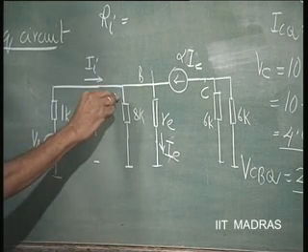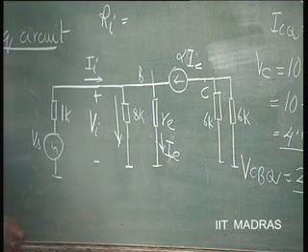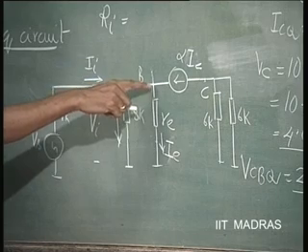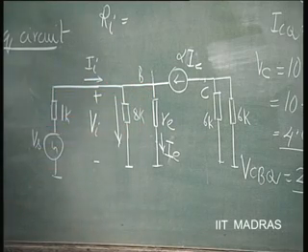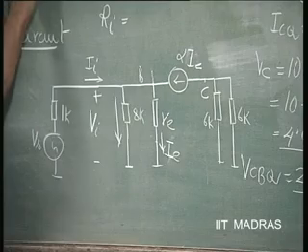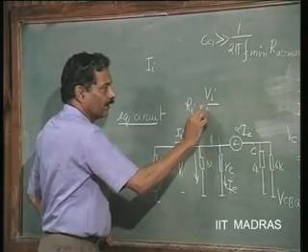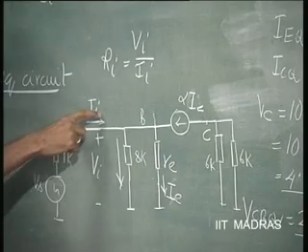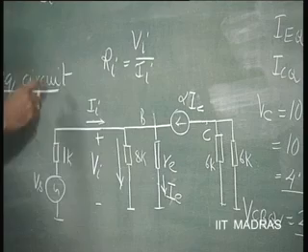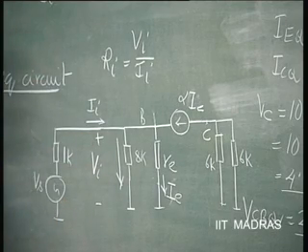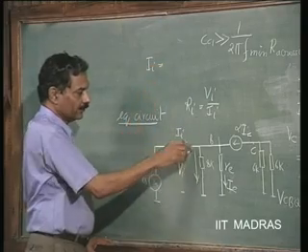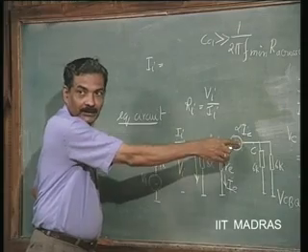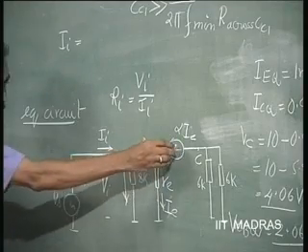So, this current here is going to be V I divided by 8K, and this is V I by R E. So, the total current I, input resistance here is input voltage V I divided by input current. So, I we will write in terms of V I now. So, I is equal to this current plus this current, minus this current. This current is in this direction.